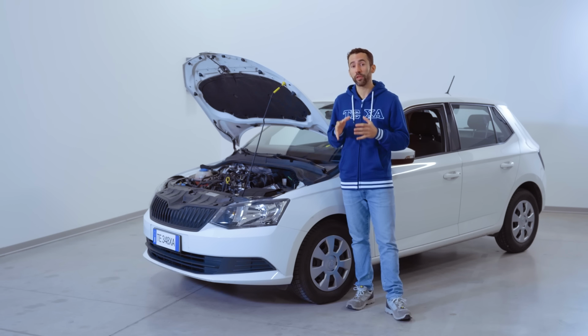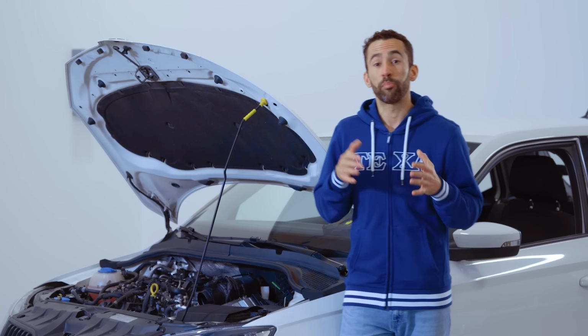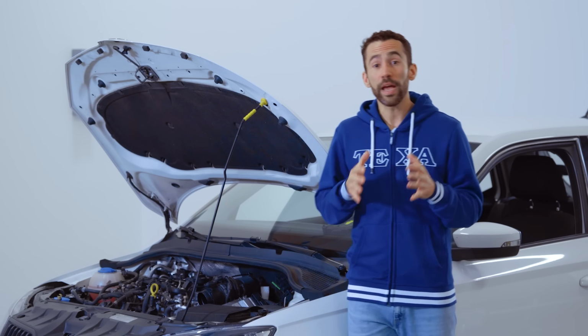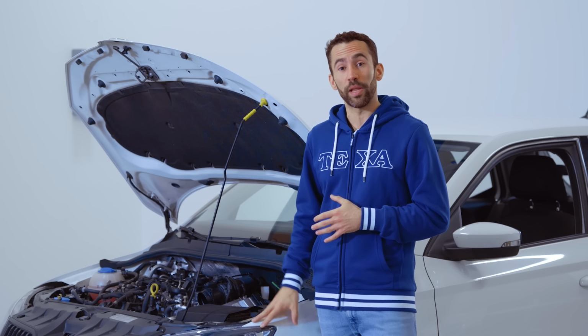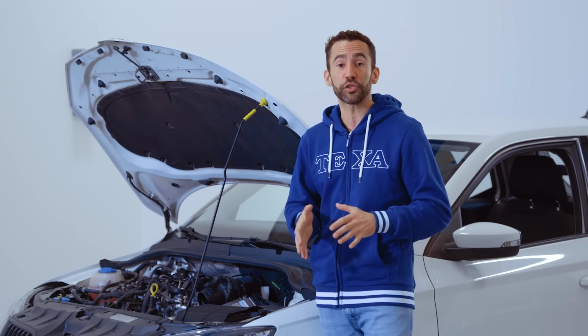The power line for the pressure sensor is in common with other components, as we can see in the wiring diagram. Our problem is that the 5-volt power for the sensors is missing. Let's see the two reasons why there is a lack of an electronically controlled 5-volt power supply: an outage, or a short circuit to ground. There are not any fuses in this type of power supply. The engine control unit manages the protection against short circuits or open circuits.